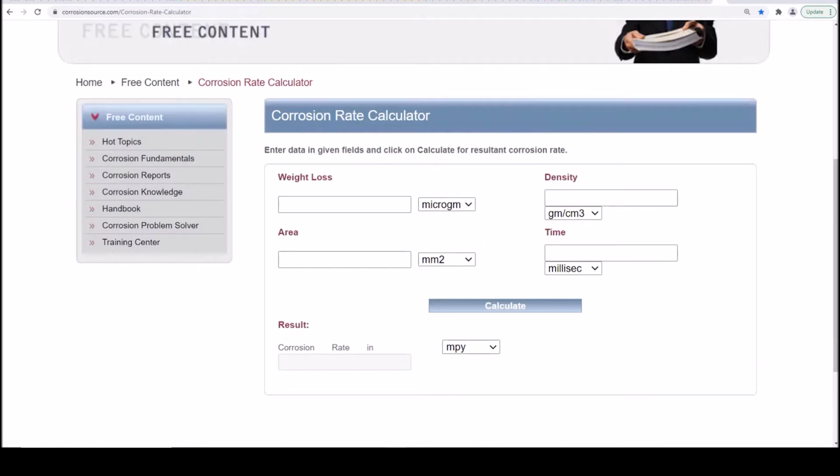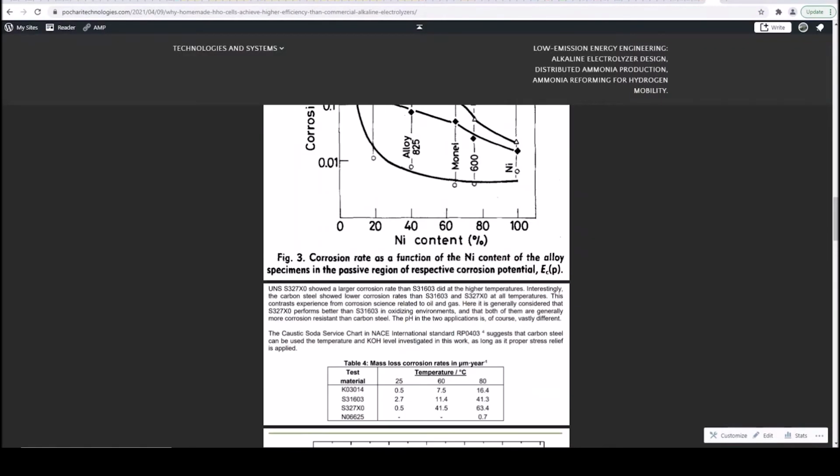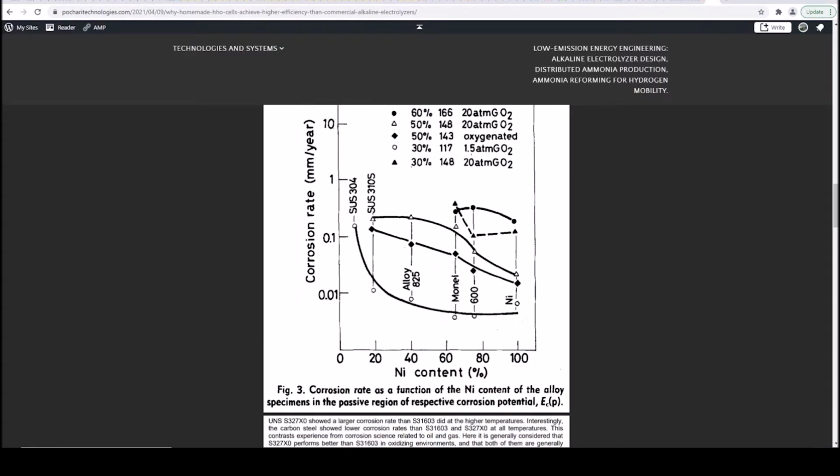So in this case, we're going to find the corrosion rate from the metal loss. I'm going to go to grams, we put, say, 40 grams, and we have 1 square meter, and then 8.9 grams per cubic centimeter, and then 1 year, 8,760 hours, and you find it's 0.17. That's a bit low, so realistically we put 55 grams, and we get to about 0.245.